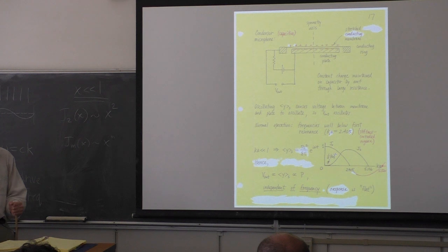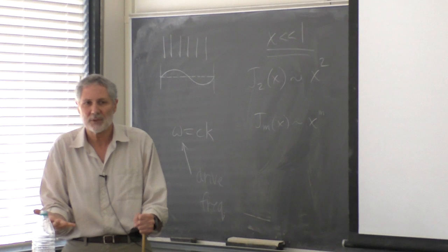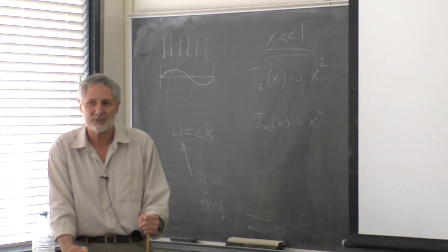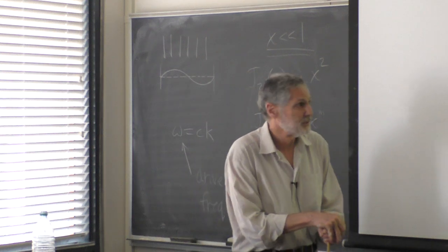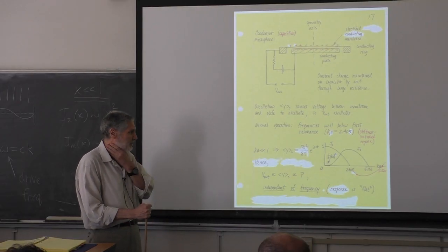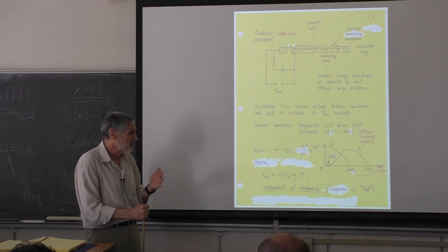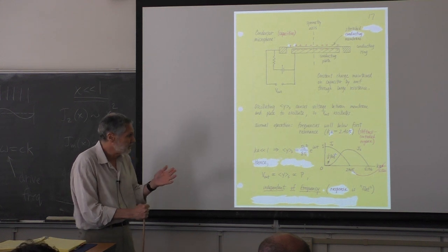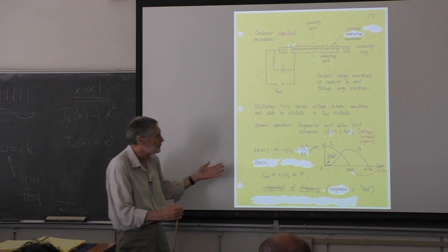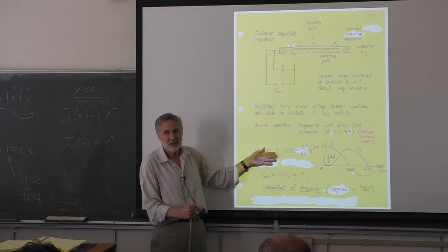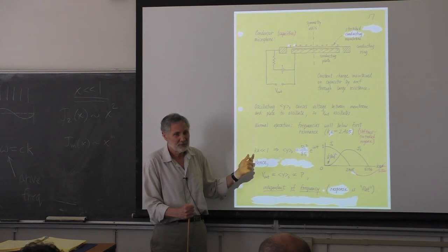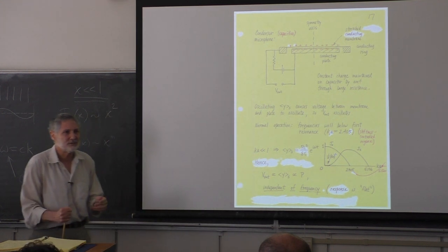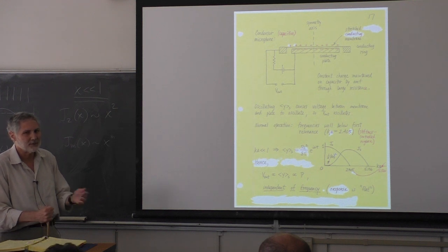We have a sound wave, we keep the amplitude. We want the voltage to be proportional to the amplitude of the sound wave. That's the basic idea here of transduction, in this case of transducing sound. We want the voltage that we pick up to be proportional to the amplitude. If we change the frequency but keep the amplitude constant, we want the voltage to stay the same. And it does, but only in the low frequency limit. So you need to be aware of that. I'm going to drill this into you starting next quarter, and then we hit it big time in the transducers course.